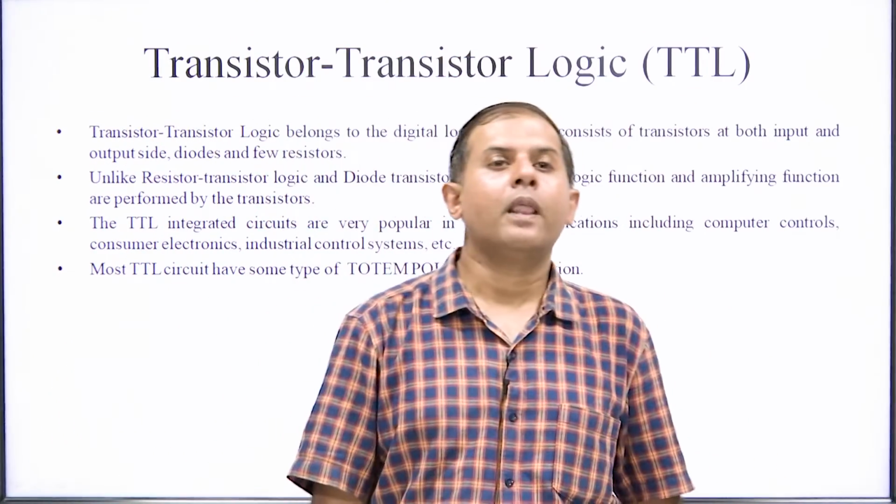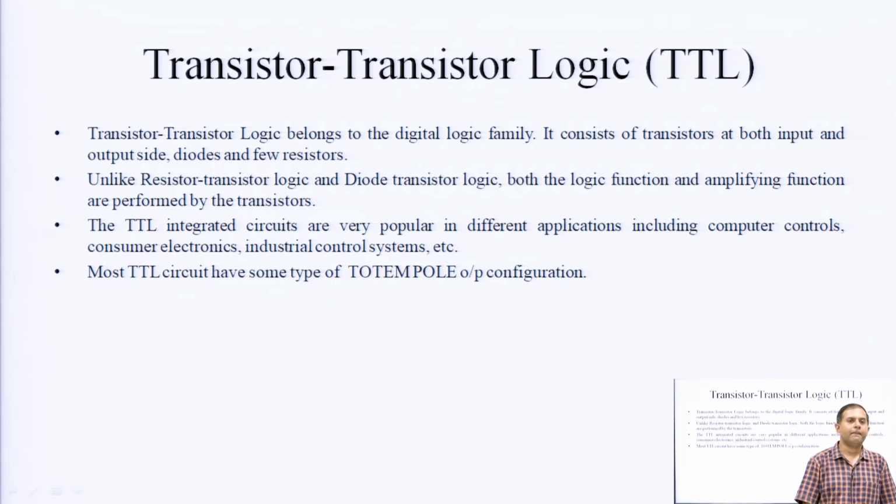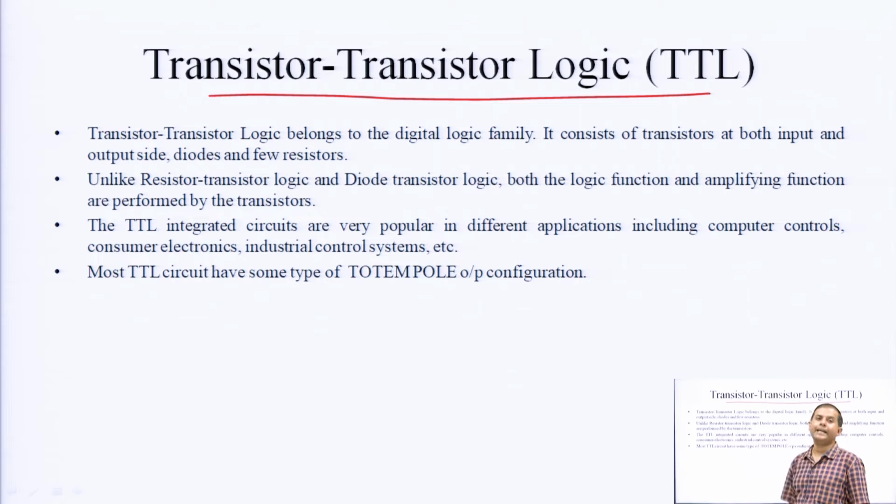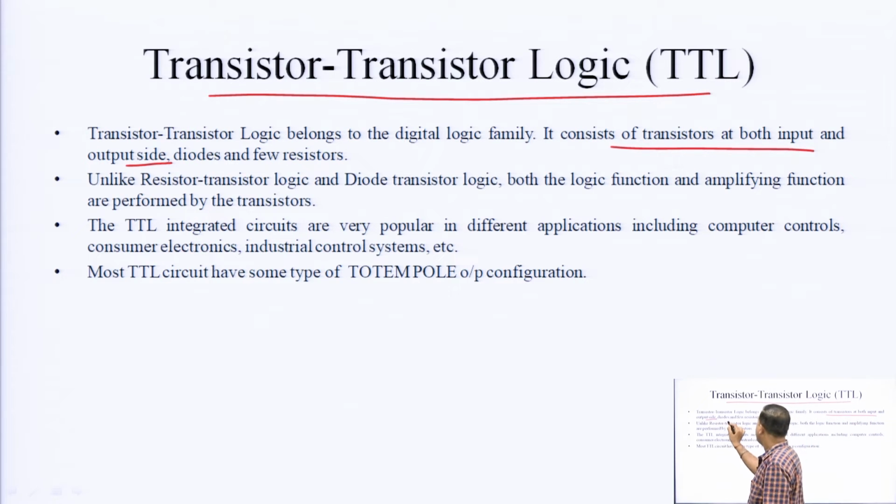First of all we will discuss TTL, transistor-transistor logic. Already in the previous lectures we have discussed RTL, resistor transistor logic, DTL, diode transistor logic and DCTL, direct coupled transistor logic. Now the turn is for TTL. It belongs to the digital logic family. It consists of transistors at both input and output sides, diodes and a few resistors.